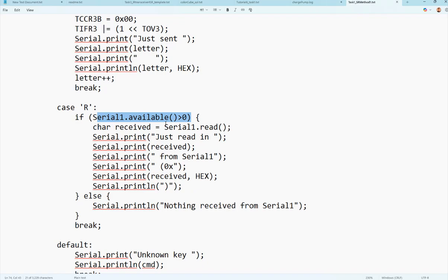So the data 10 bits are being sent. Once you press S, everything will be executed, and all the 10 bits start with a pull down 0 starting bit, right? 0, and then all the byte, and then pull up. So the 10 bits will be in the air, and then the decoder will receive it. Does the receiving module of the UART start receiving that 10 bits, or does it have to wait for the R press event? It will start receiving, okay?